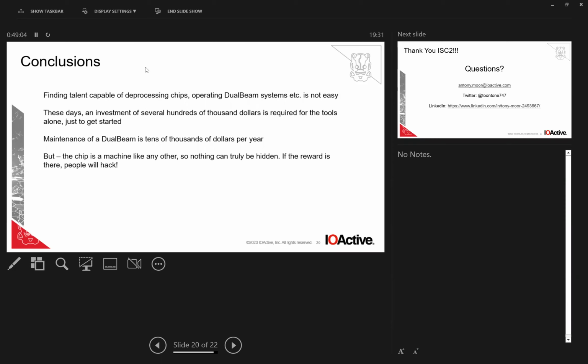The components were exactly the same as they should be, but somebody had added what looked like a passive component, but it wasn't. It was a small IC. So that is possible. You could take something that's really a passive component, a resistor or a capacitor, and replace it with something that does that job but is actually doing extra stuff.